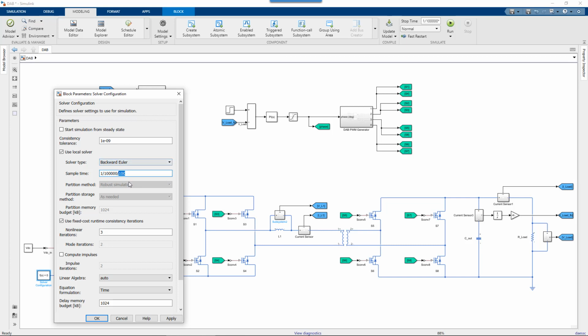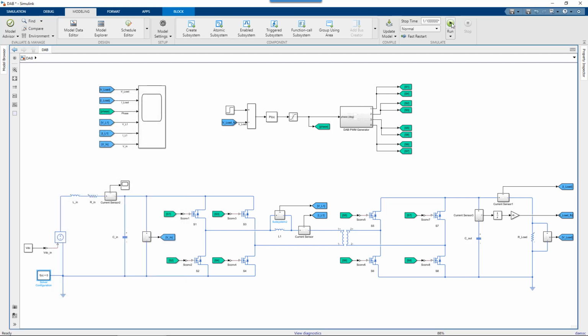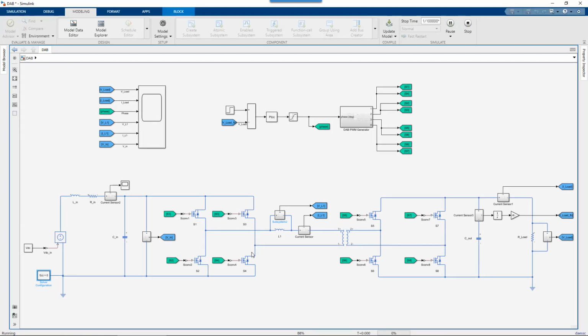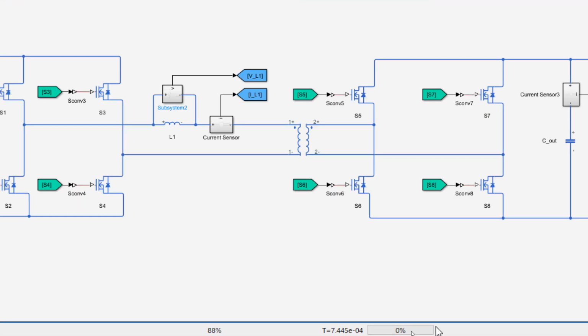This is more likely to be able to handle them, but you also have to dial the step size down really low. So I could dial this down to 1,000 steps and essentially brute force the equations. But I'm not going to run the simulation the whole time because it's just going so slow. If you look down here, it's just taking forever. Now, it will give me a pretty good idea numerically what my model is doing.